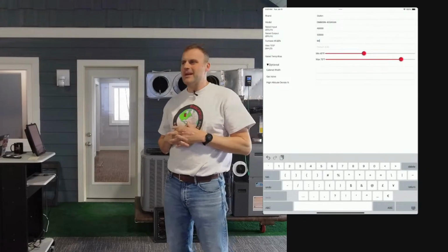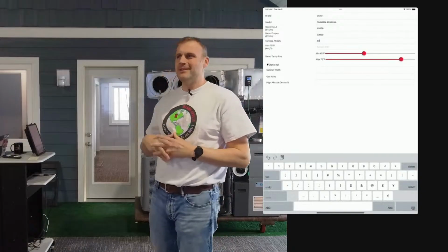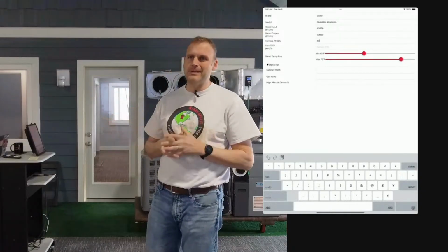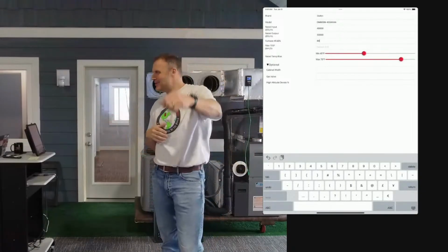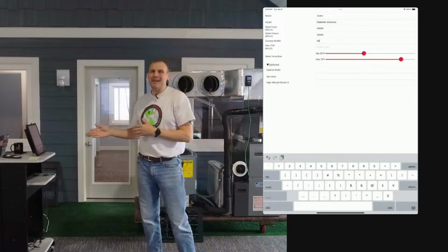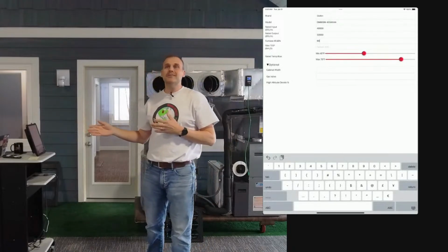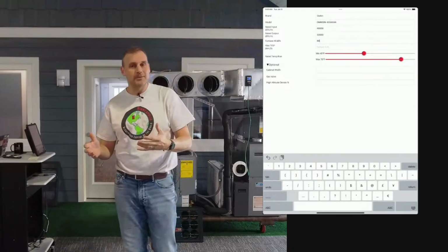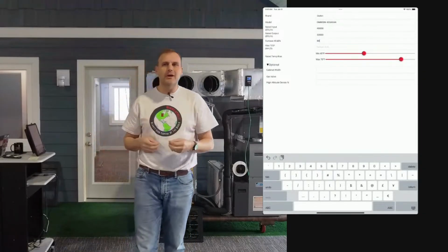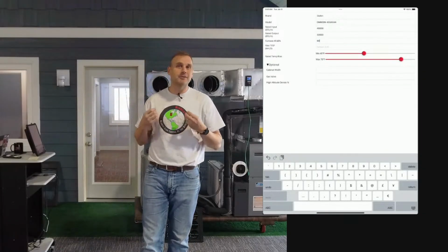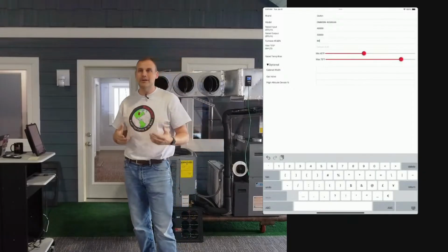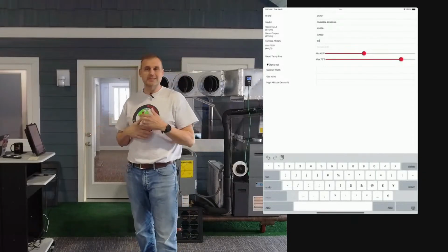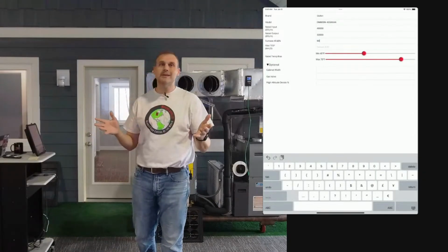I wanted a super user feature that says, let me enter my own TESP. We won that one. Yay, go us. You toggled it on in the settings, and then you could set the total external static pressure of the system, okay? This is probably the hardest data input that you're going to have to go find when you're putting in information for testing of cooling, heating, or anything.